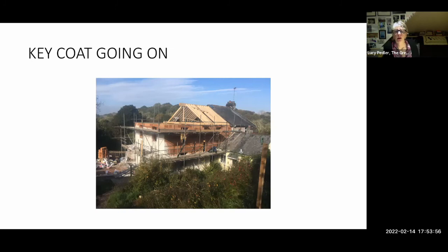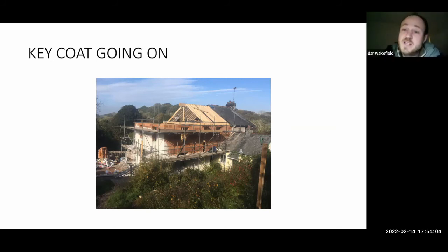Mary says, if your air tightness is your internal plaster, how do you deal with integrated services? They're all chased out. Where necessary, we chase out with a grinder or a router, and then we plaster the channel before you put your surfaces in. It's moderately time consuming, to make sure that air tightness layer is continuous behind your surfaces, and then you plaster it all in.